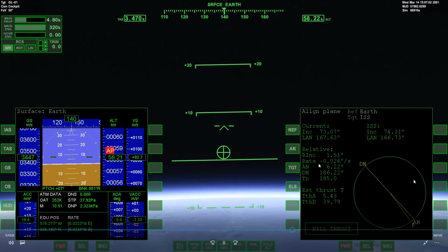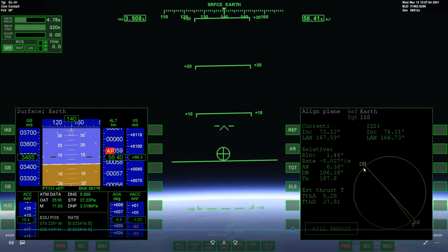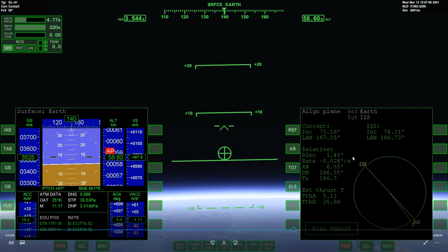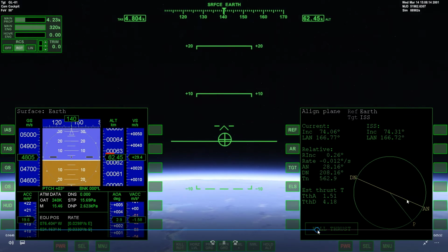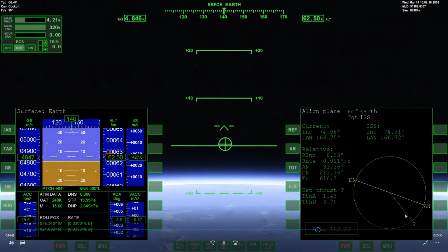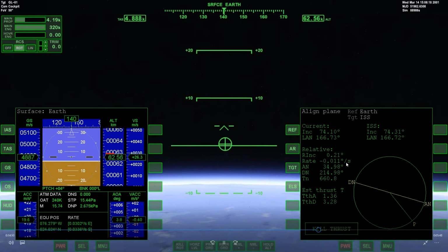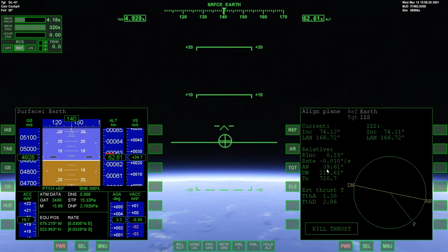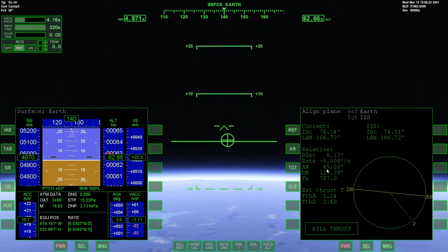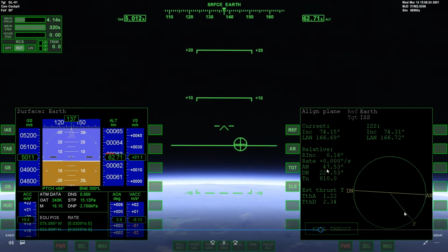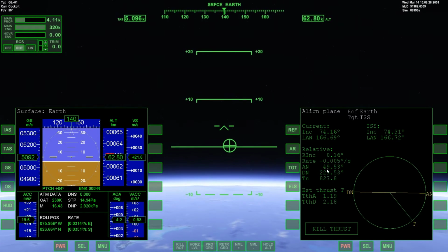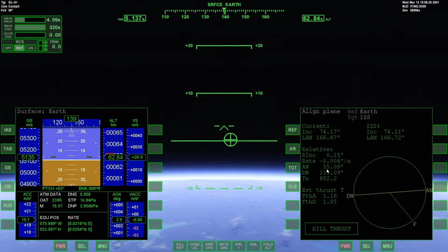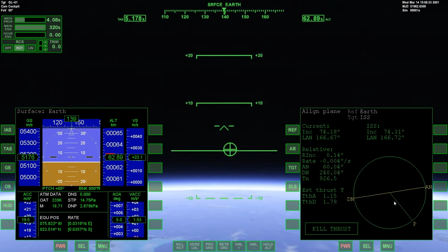I talked about how it was pivoting around on our position and to try and keep that at a 90-degree angle. Let me just find that very quickly here. You can see how it's spinning around right now on our position. And I talked about if we could keep that at a 90-degree angle between our radius vector here, our position, and the line of nodes. If we could keep that 90-degree angle there, that relative inclination would be held at the lowest possible point.